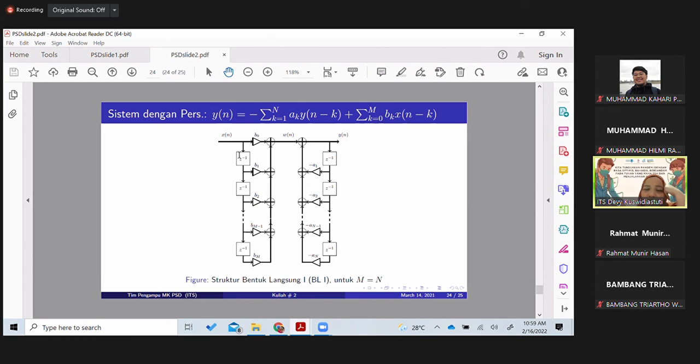And then you could see that there is a shift register here. So you could understand from the drawing that here you will get xn minus 1. And if you go through another shift register, then it will be xn minus 2. And here you multiply with B2 and sum up with the rest of the signal.